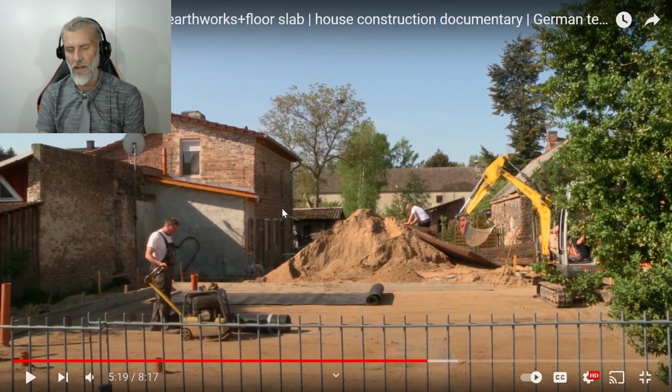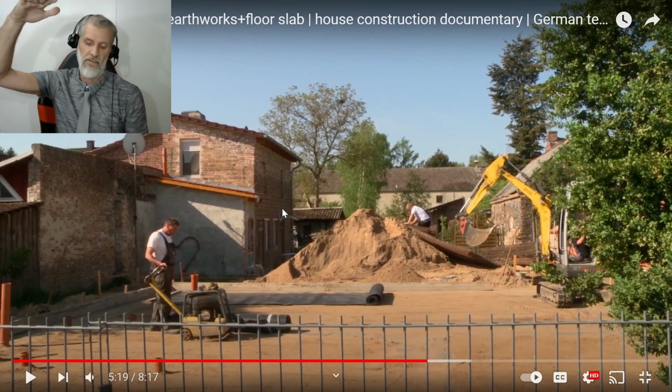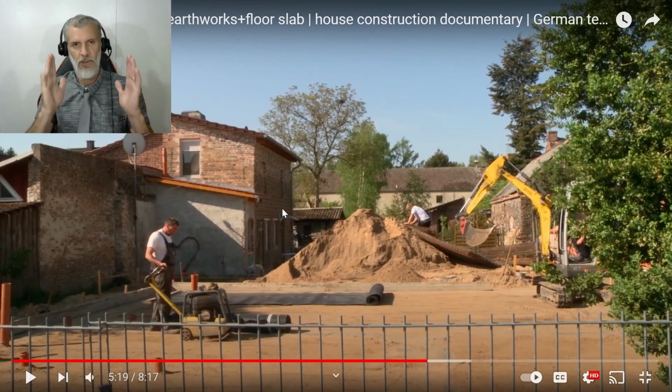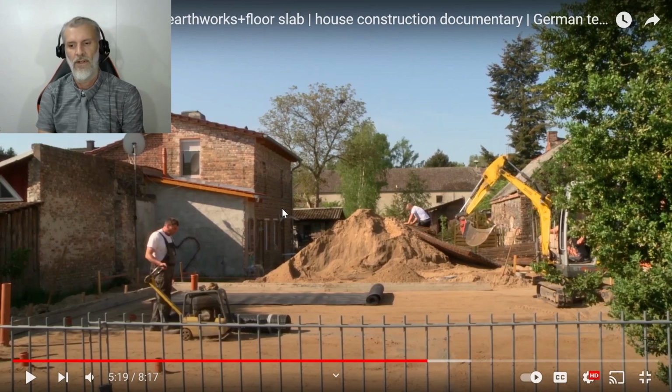Okay, so the first thing I notice is that there's no footings. In Australia, the first thing that is done is what's called a footing. So all your supporting walls will have a footing, depending on where you are, depending on the council regulation, probably 900 mil, so nearly a metre deep, and then I think it's 250 wide. So it will actually be a footing that goes all the way through underneath first, and after that dries, then this is done over the top.